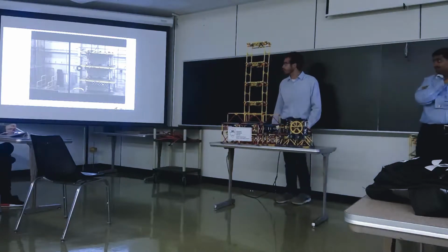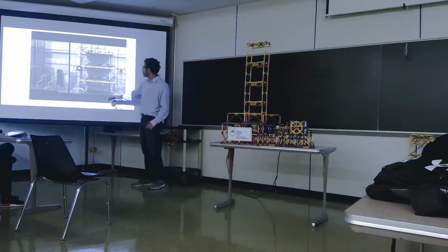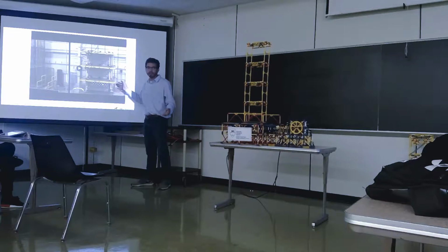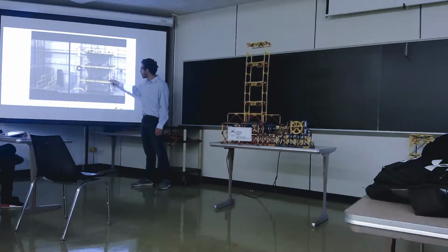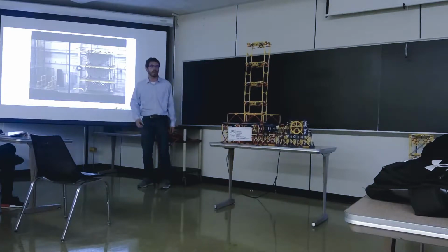Okay. So this could be idealized to a multi-degree of freedom system, and you could simplify it to essentially 4 nodes: 1 at the base, and then first level, second level, third level. And each of these plates right here, as you can see, is kind of large. It's a big chunk of mass, essentially. So you have masses, and then stiffness comes from the plates as well as the columns, and then the damping comes from the energy dissipation that's inherent in the system from the yielding of steel and such.